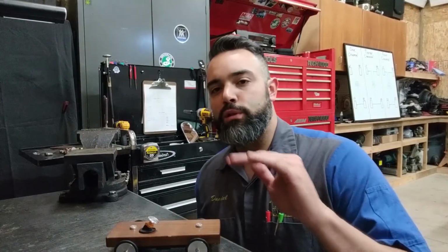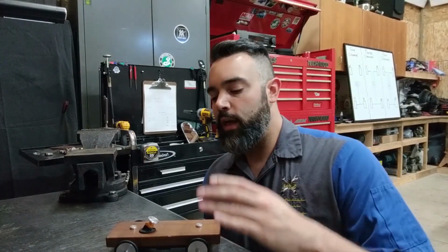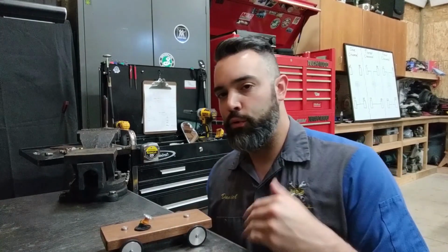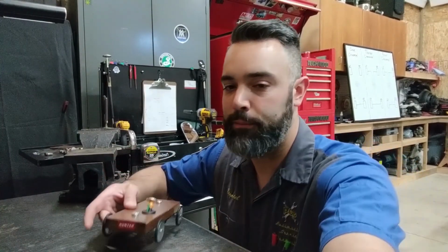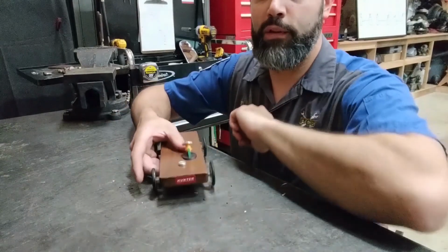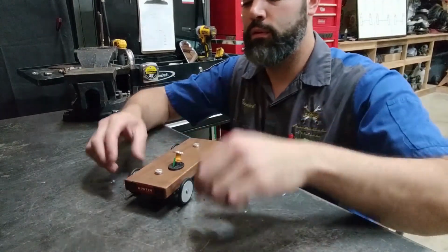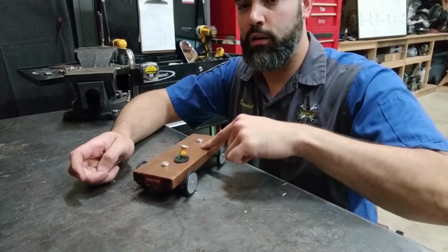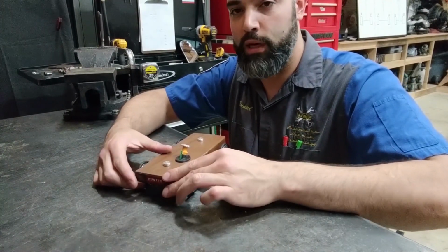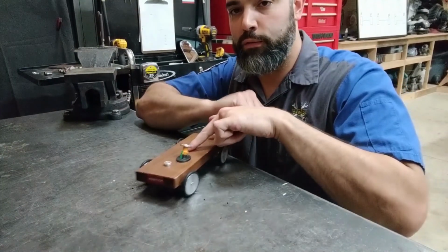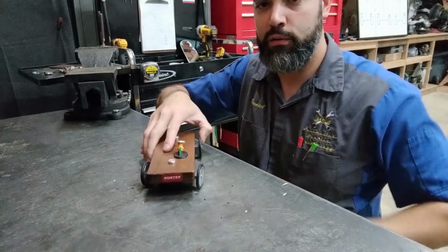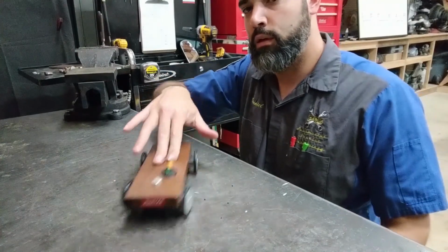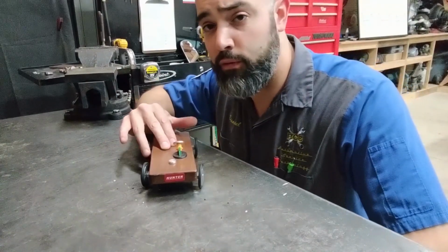If a person were to step on the brakes to the point where slippage occurs and a lockup happens, then it either happens in the front or the rear or both. If the lockup occurs in the front of a vehicle moving straight along, and they want to steer and avoid an object, the tire needs to be moving in order for that to happen.